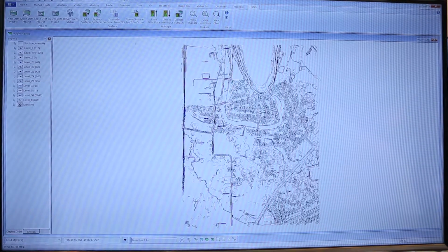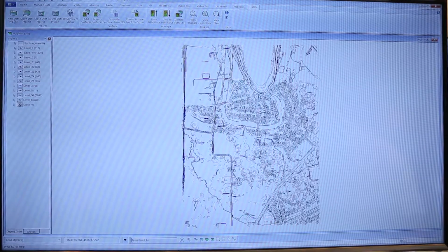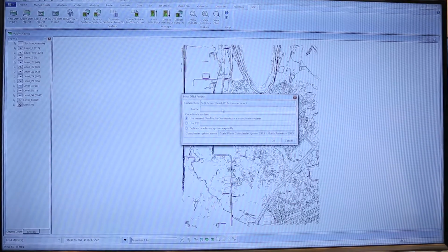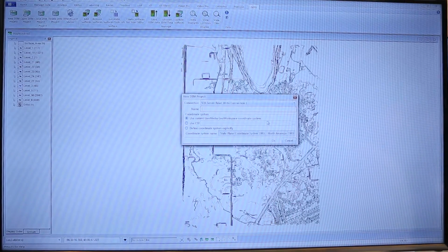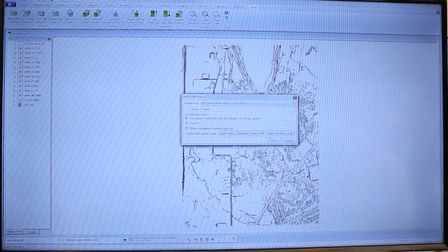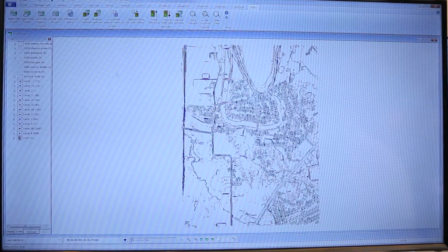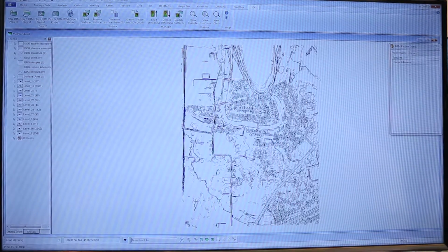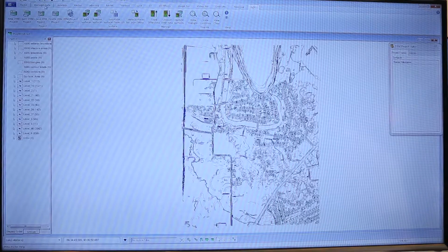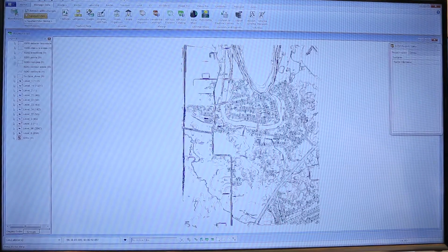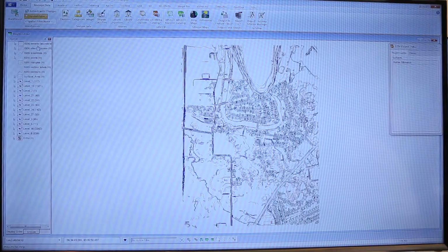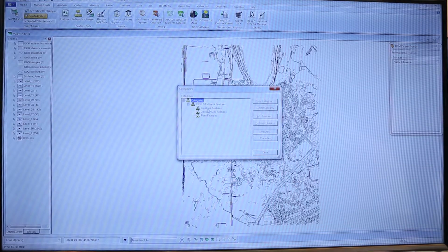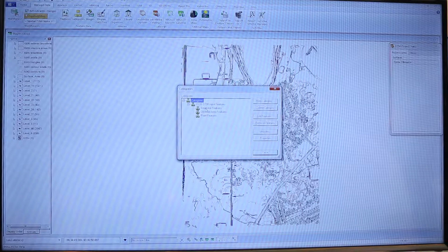Okay, first we'll create a new DTM project. We'll select our SQL Server connection and give it a name. And I'll bring up the project status, so we don't have any elevation data at this time. Now, when we created the project, we added some predefined categories to our map legend, and we also set up some predefined GIS features, which will be used in the elevation creation process.